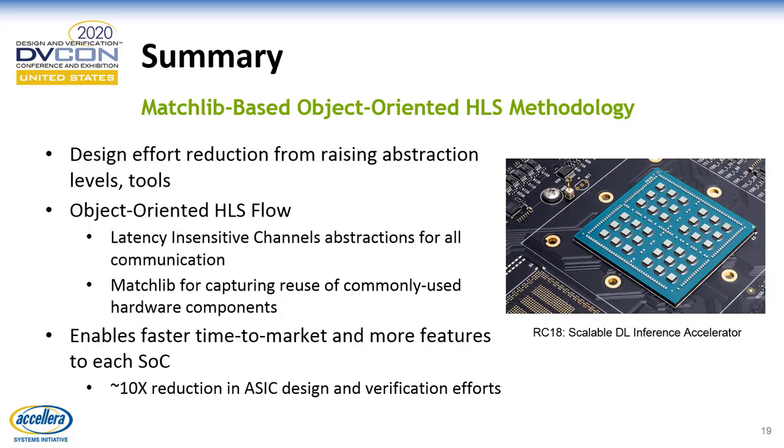To summarize, we presented a MatchLib-based object-oriented high-level synthesis methodology that achieves a significant reduction in design effort by raising the level of abstraction and using automation tools in the design process. Our object-oriented high-level synthesis flow, consisting of latency-sensitive channel-based abstraction and MatchLib, ensured significant reuse and modularity in the design process. This can potentially enable faster time to market and more features in each SoC. For the test case of the RC18 deep learning inference accelerator, we achieved about 10x reduction in ASIC design effort.